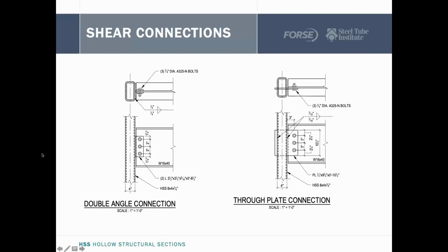Next, looking at the double angle connection here, this is going to give us even more capacity. Again, we're delivering that load to those sidewalls, plus we get the double angle connection in the beam web to give us a little bit more capacity if we need that.